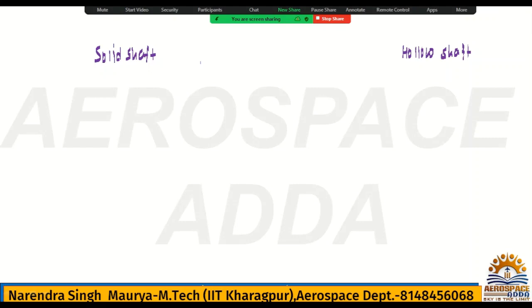The criteria will change for the different cases. If you are talking about the strength comparison, then you talk about the same weight, same material, same length, and same maximum shear stress. If you are talking about the weight comparison, then what will be the constant things? Same torque, same material, same length, same maximum shear stress, like that. Okay, so I will write both cases. We have a derivation, but I say the derivation is not required.